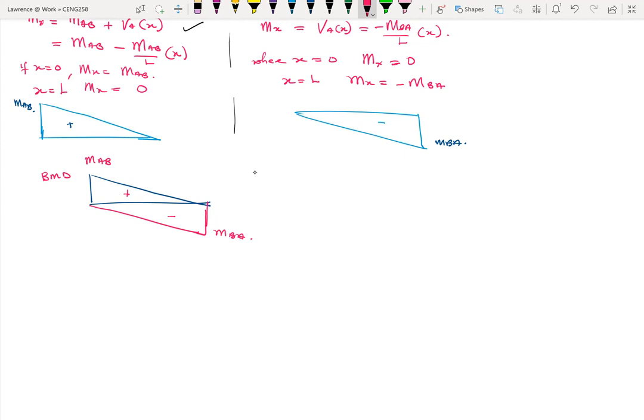We know that in the conjugate beam approach, shear force in a conjugate beam is the same as the rotation or the slope theta in the real beam. Okay. And then we know that the bending moment in the conjugate beam is the same as the deflection in the real beam. We've done these ones already. So we are only applying that information from last semester here. Okay.